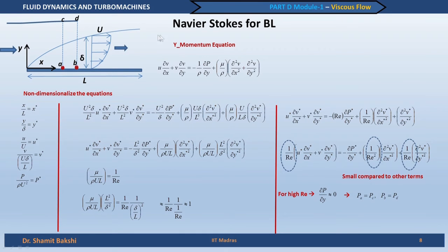Now we already saw for the case of flow over a flat plate, delta P along a streamline is 0 because delta U is 0, using the Euler equation for an inviscid flow, of course this flow outside the boundary layer is inviscid flow. So you can use the Euler equation, and if delta U is 0, delta P will be 0. So that means PC is equal to PD. So if that is the case and you use these equations, what you get is PA is equal to PB, and you can do this for any set of 2 points drawn within the boundary layer.